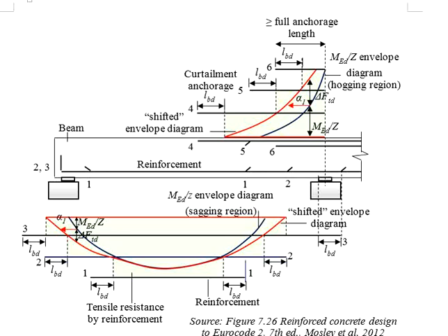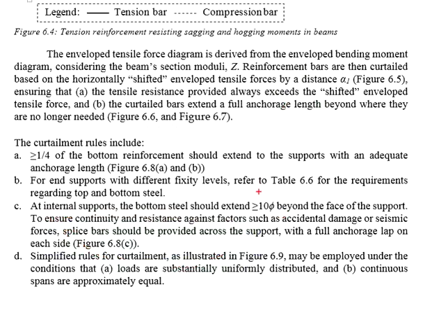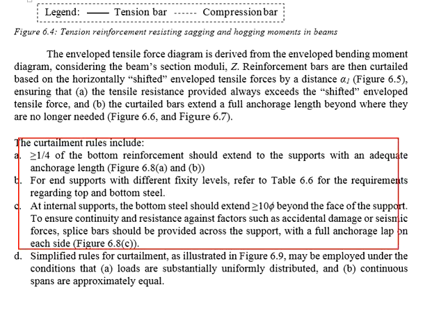derived from the bending moment diagram using the formulas of NEd per z. The reinforcement should provide sufficient resistance withstanding the tensile force along the beam span, and the reinforcement may be terminated at regions which are unnecessary, provided the resistance is always greater than what is required, as reflected by the shifted envelope diagram. On top of those, there are several additional curtailment rules.